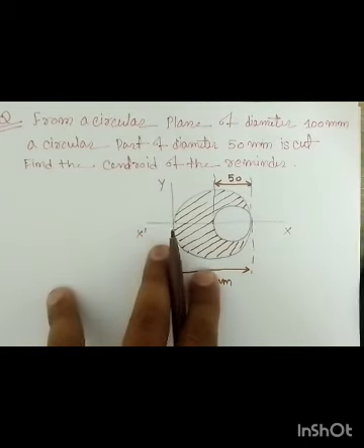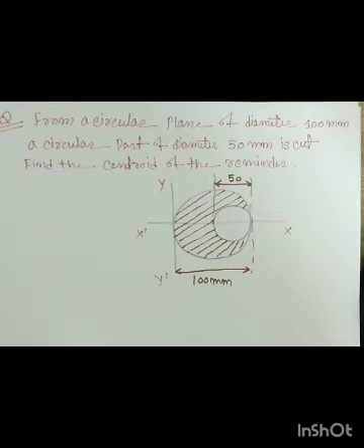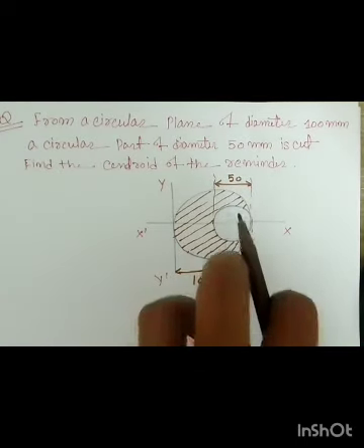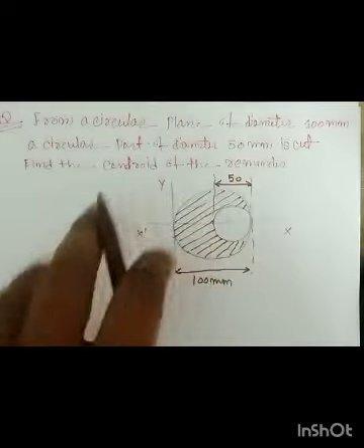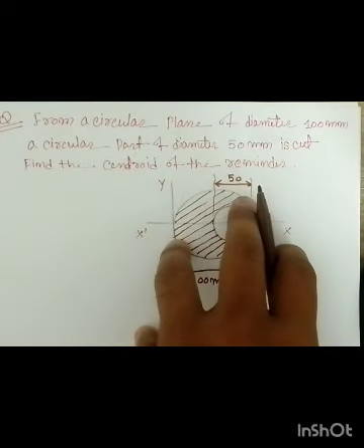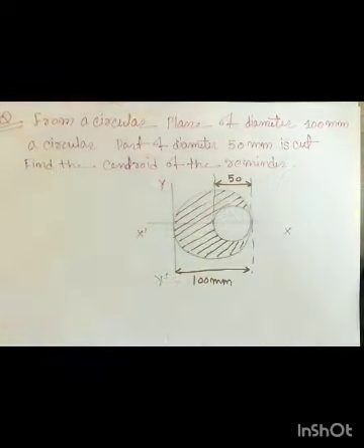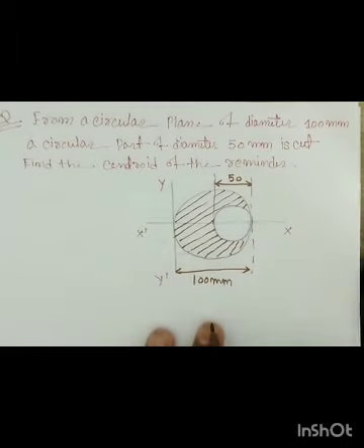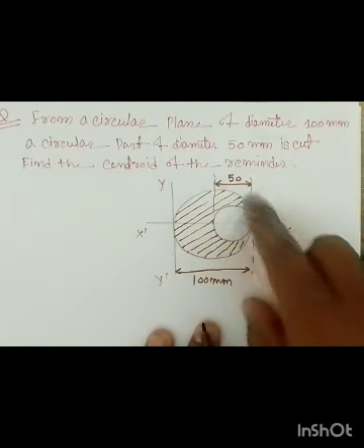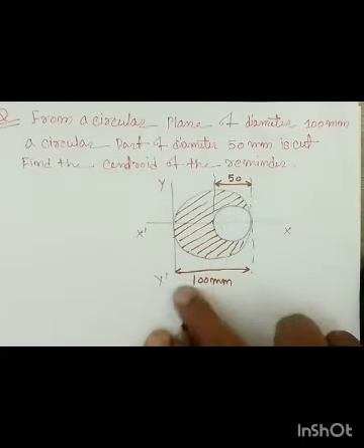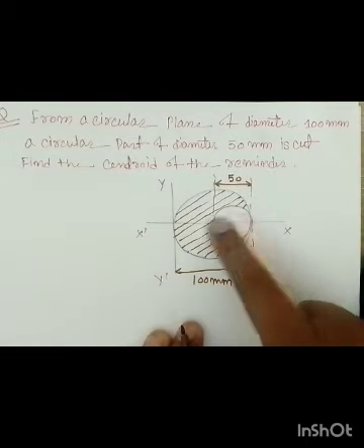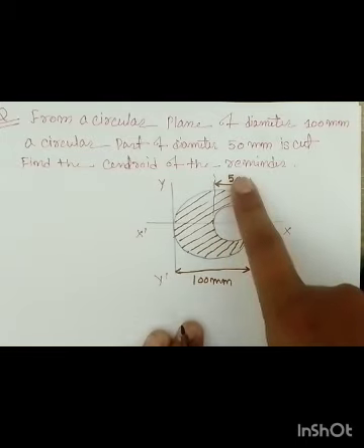So for the cutout section, in the analytical method, we are adding the area moment like a1 x1 plus a2 x2 plus so on. But in a cutout section, whenever the material has been removed, we won't add, but that particular part we should subtract, right? So two circular plates are given. One has a diameter of 100 mm, and the other is the cutout section. This hole has a diameter of 50.